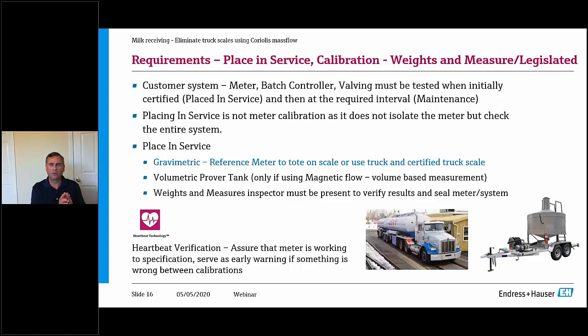So as long as you stay within that 0.2% accuracy, and you're doing it repeatedly, 3 times over, it's got to be repeatable. You can't have one where you're 0.2%, and then the next one is 0.3%, and then the next one is 0.2, and you do another one, 0.2. They have to be repeatable, consecutive, to make sure that every time you have a truck come through there, it's going to do the same thing. But generally, that's what you do. Do it 3 times there, and then you say, okay, now we're good. We can put this in operation.